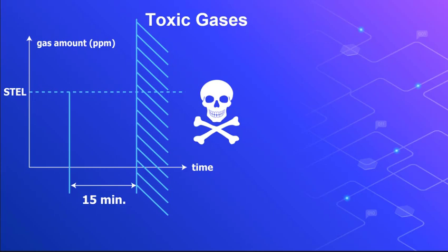300 ppm is also the STEL level for the carbon monoxide, which is the upper limit we can be exposed to for 15 minutes. Carbon monoxide gas detection in parking lots is designed and implemented based on these levels determined by the World Health Organization.